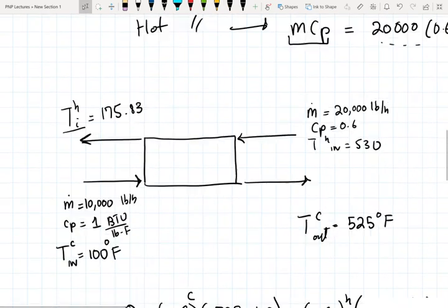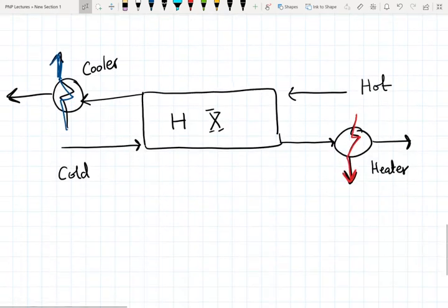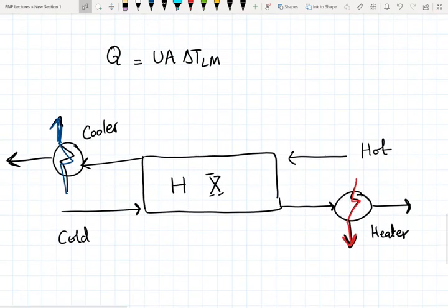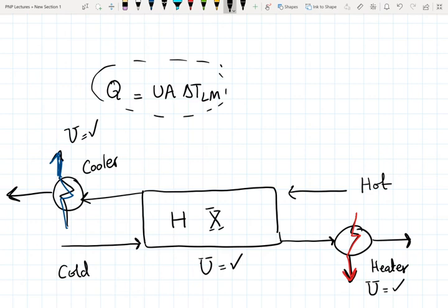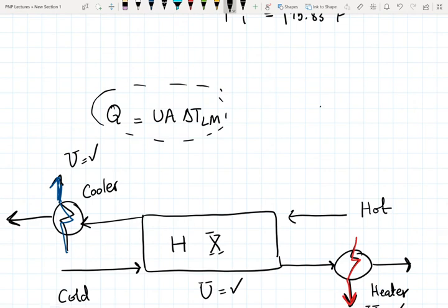Once phase changes become involved, the heat exchange network design becomes more complicated. And once you know the heat transfer coefficients for the heat exchanger and the heat transfer coefficients associated with the heater and cooler, you can determine the sizes of your heat exchangers by using the design equation. And that pretty much sums up. Just a closing remark: the impact of minimum temperature.